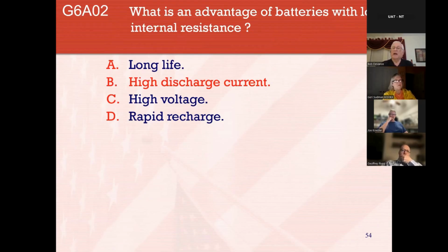Now, what batteries would have lower internal resistance? Almost all of our lithium-ion type batteries or LiPo batteries, lithium iron phosphates, etc. The nickel metal hydride batteries that we used to see were very popular have a relatively low internal resistance. Our alkaline batteries have a fairly high internal resistance. They're not very efficient in the long haul. So for our radios, we generally want those good batteries with low internal resistance so they can give us more current and not hurt the battery and continue to give us good service life.